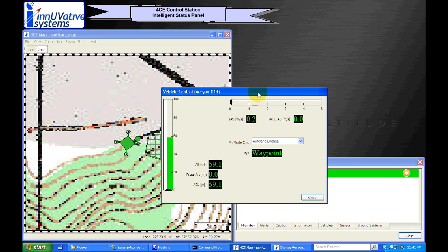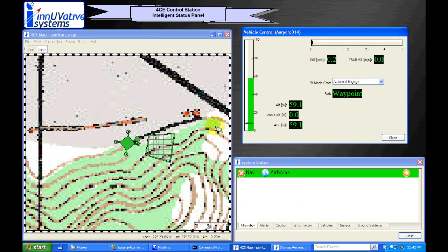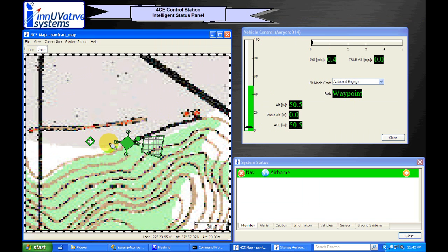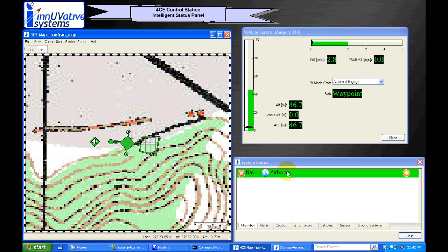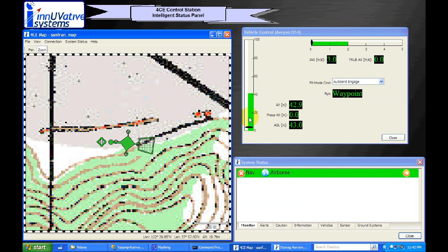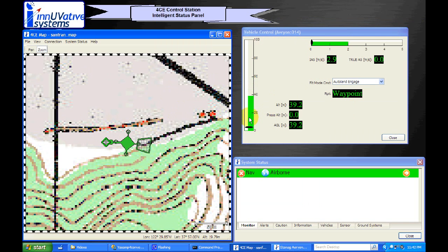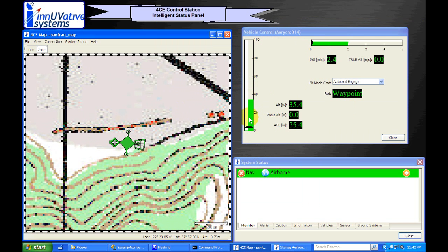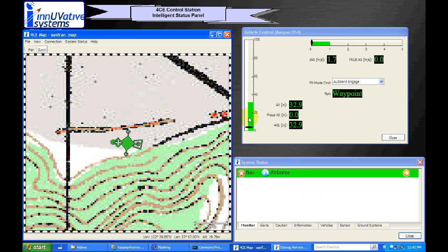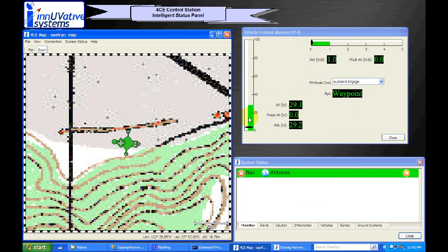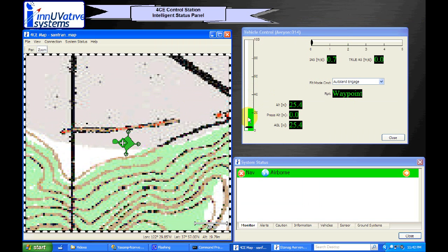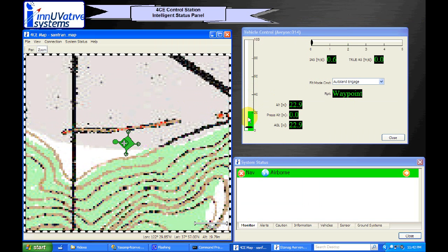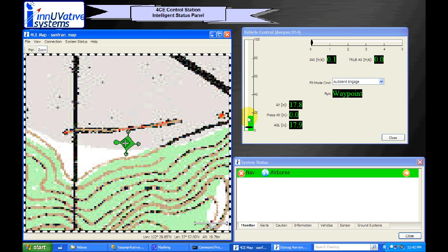Finally, the last thing we'll notice here is that whenever I go in and change my altitude down to something low, I'm going to bring back the altitude warning that we saw earlier. I want to see the vehicle come down and drop below 12 meters. We'll see the red warning come back in a solid red state, because the flashing red is reached at 8 meters. However, as it drops below 12, I'll bring it back up above 12 again so that the warning gets cleared very quickly. And what you'll see is that the warning doesn't disappear, but instead turns gray.